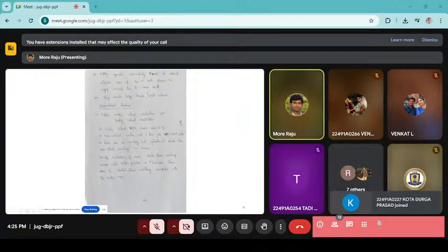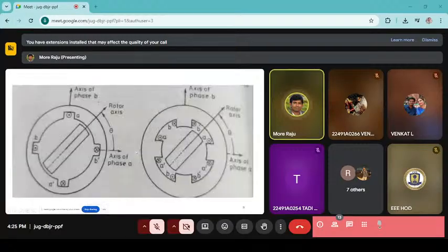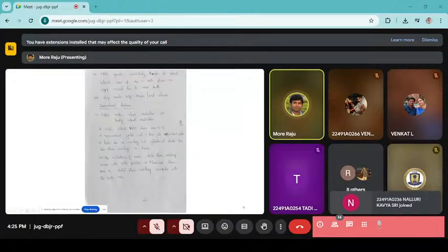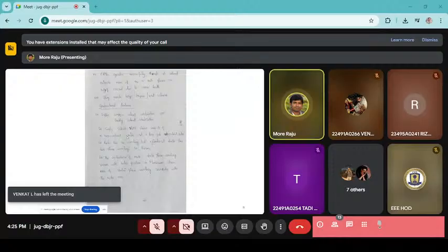The rotor has no winding, but the cylindrical stator has a two-phase winding as shown, that's why you see A dash phase, B dash phase. Whether it is singly salient or doubly salient construction, they are basically limited to a two-phase system.